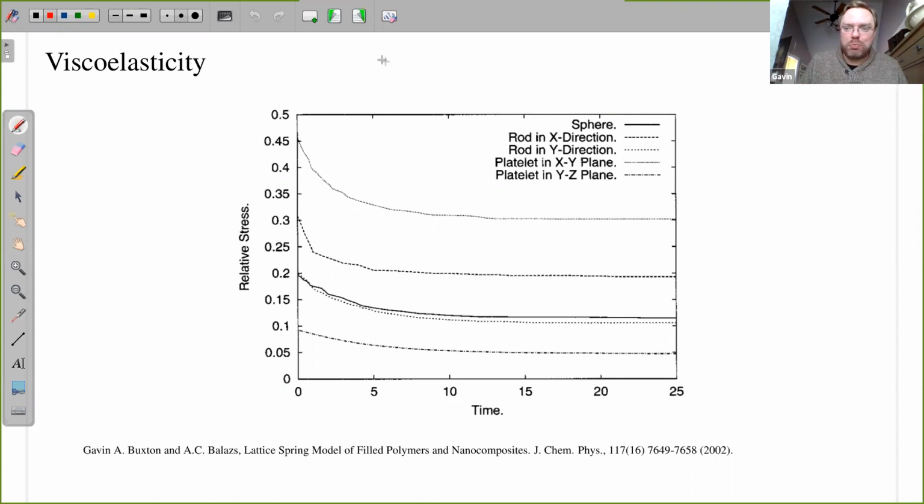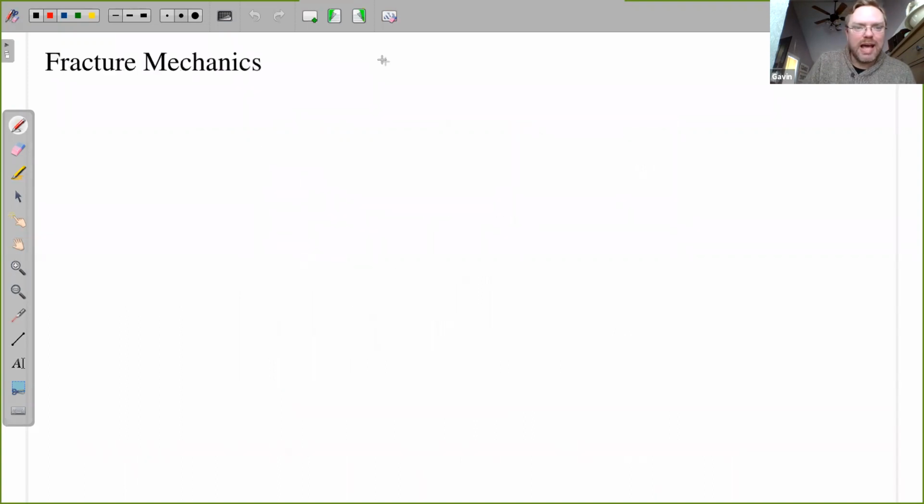Now, to incorporate these viscoelastic behaviors, what you generally do is just put a dashpot in with the spring, right? It's really that simple. You're just allowing the displacement to have two components. One is elasticity, and one is because of the flow in that dashpot. So this is the Kelvin-Voigt model of viscoelasticity.